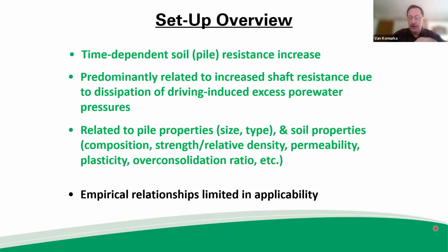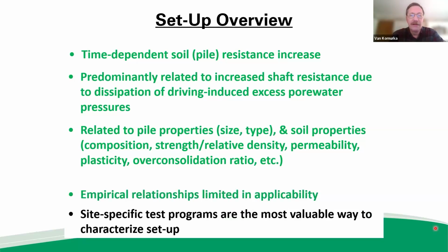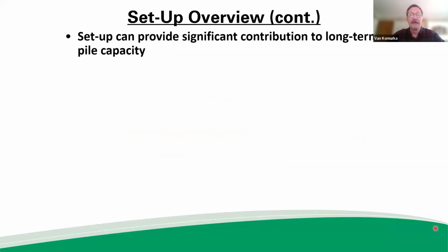And so, given that, site-specific test programs with given soil types to be tested in the soil conditions at a given site are the most valuable way to characterize setup. You can't look at a soil boring, you can't take constitutive soil properties, and get a real accurate estimate of setup. So really, test programs are the best way to go about it.